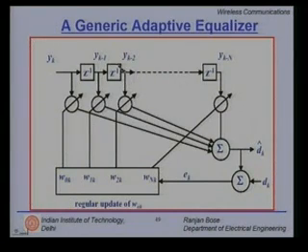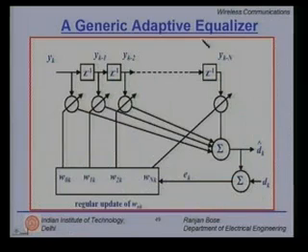In fact, this necessitates the need for some kind of an adaptive equalizer. If the channel has a very large delay spread, I should be able to use more delay elements and more tap points, and then when my mobile moves to a region where the delay spread is much shorter, I should be able to undo some of the stages and retain only the necessary number of tap points. We will see today that there is one kind of implementation that precisely does that.